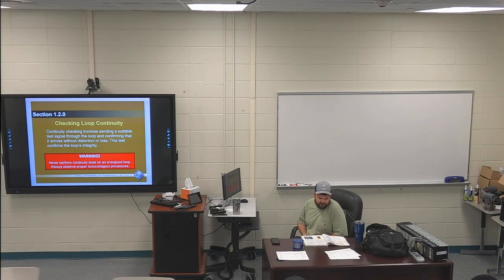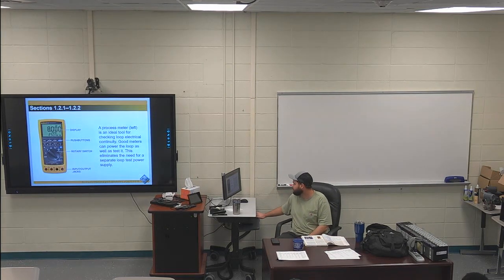Electrical continuity test, 121. Second paragraph, last sentence. You'll have a couple questions come out of that. Ideally, you should select a device that can energize a loop using its own power supply. I keyed in on that. Using its own power supply, allowing the loop's normal supply to be locked out during testing. So that's where you can have a process meter that can actually put out a